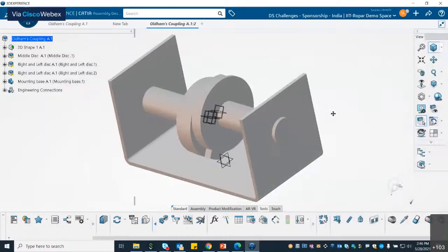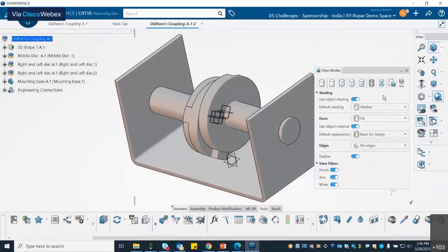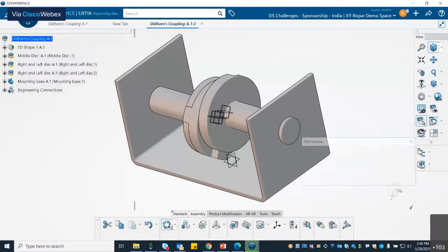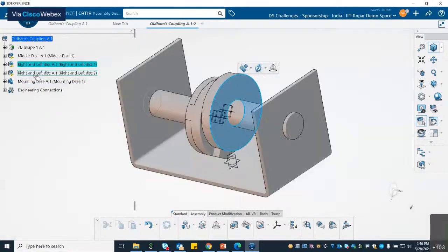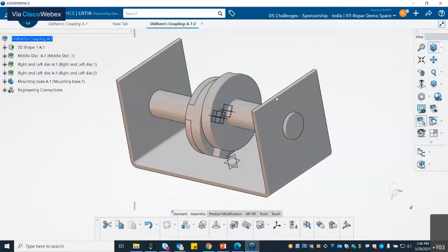So now you see it's not showing the material. For that, just check that you are in the material tab, showing grading, shading. Okay, and yes, update your assembly. So what problem am I getting? We already applied material in the XDesign app, so it will not be able to show the applied material on the assembly tab also. So instead of applying material, we will move forward to create the mechanism.